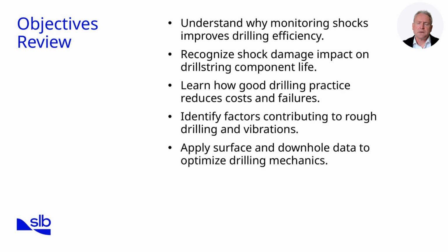We then looked at how good drilling practice directly translates into savings by reducing trips, extending bit runs, and lowering maintenance costs. Following that, we identified the major contributors to rough drilling: formation properties, borehole condition, well path geometry, and hole cleaning. Each was shown to play a role in vibration.